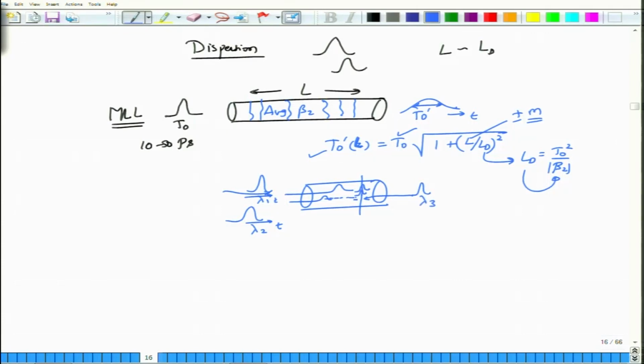As the amplified lambda 3 comes out, you can take it out, and by knowing the length, which you can anyway calibrate properly, you can know the attenuation that the lambda 3 signal has undergone. You can remove that attenuation, and then by looking at this particular point where they are interacting, you can find gamma as well as beta 2.